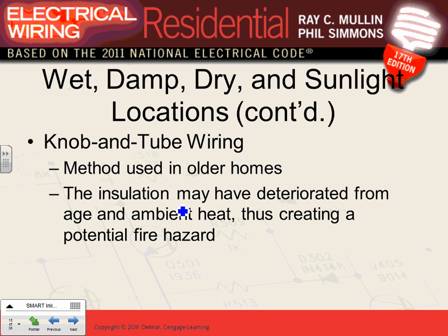So yeah, they say tap Romex off of old knob and tube. They T-tap Romex off of old knob and tube. But you have to put a junction box though. I'm just saying the old stuff, like what you find. Yeah, they would T-tap Romex just on the knob and tube, without the box or anything. Yeah, without the junction box.